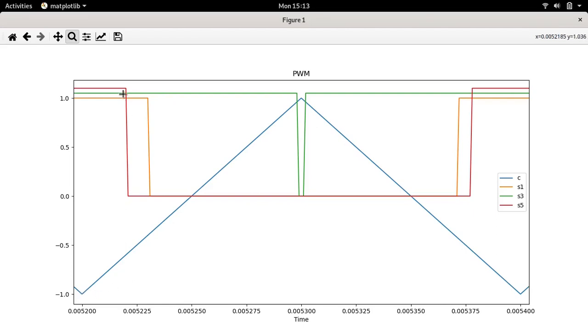All right, which means until this instant when device S5 starts getting turned off. So here, see here, device S5 starts getting turned off, which means device S6 will turn on. Remember, always the upper and lower devices in a leg are complementary, which means if S5 is turning off, S6 will be turning on. I just didn't want to put it here because then there'll be too many devices and you won't know what is what. Okay, that's all.